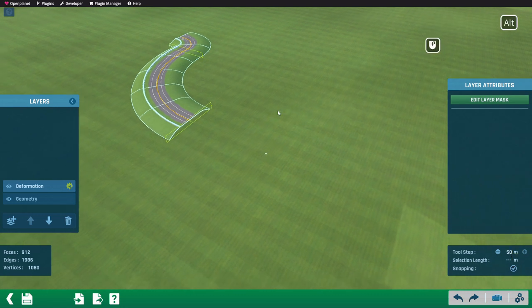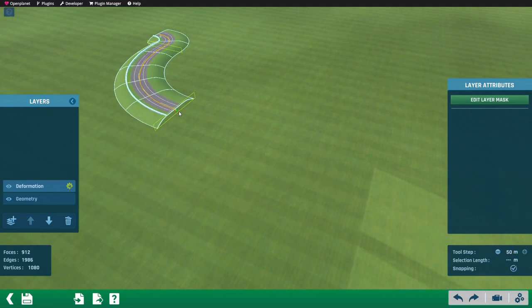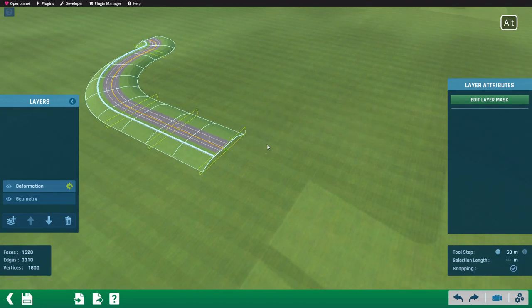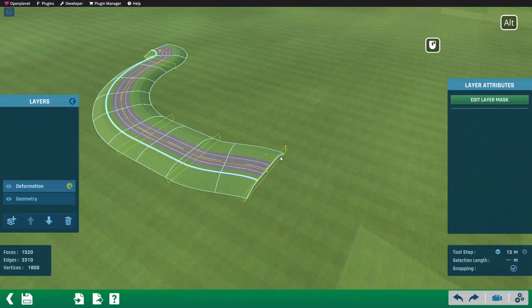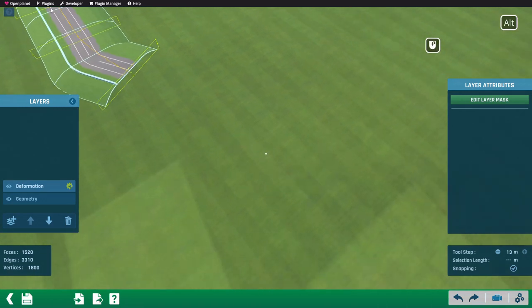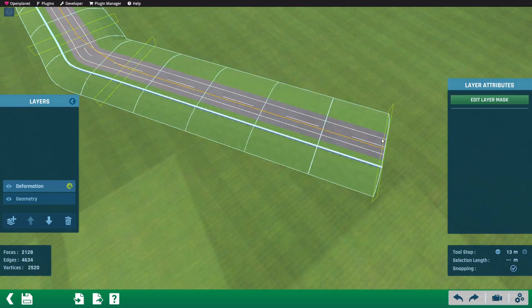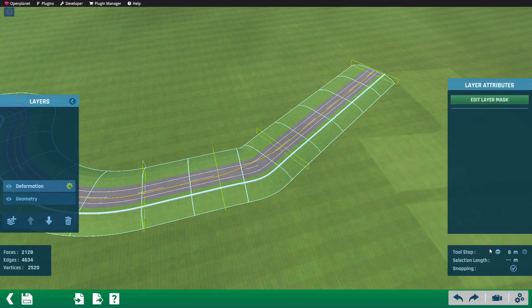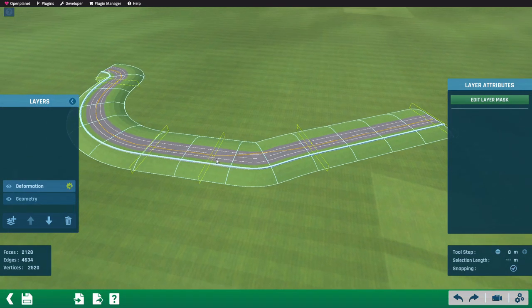Simply applying these formulas to the position of a new control frame works without a problem for angles between 60 degrees and 120 degrees, but below and above, additional problems occur. When you create a small angle turn below 60 degrees, you can notice that the actual turn will be tighter than expected. The exact form of such small angle turns also depends on the length of the deformation. The easiest attempt to fix this is to move or to delete adjacent control frames. This can often solve the problem, but the exact form of the turn gets less controllable.